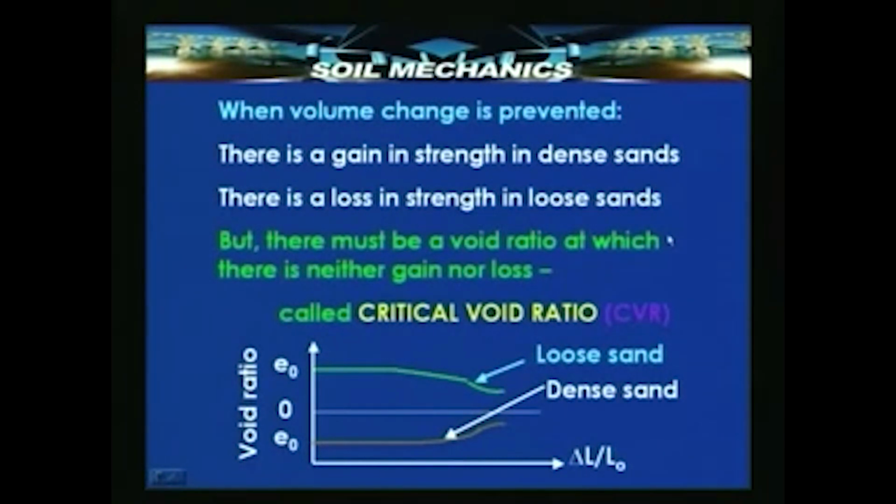But this shows that there must be a void ratio at which the sand is neither dense nor loose, and therefore neither gains strength nor loses strength. Take a look at this diagram below. This shows void ratio versus the axial strain in a typical triaxial test.